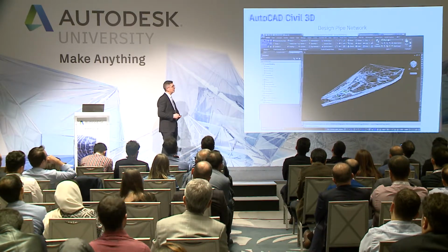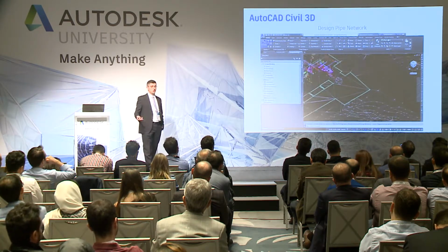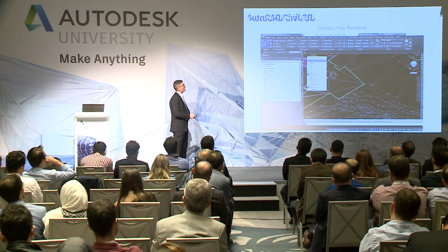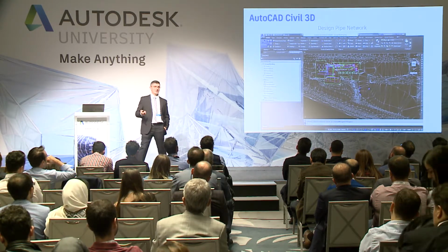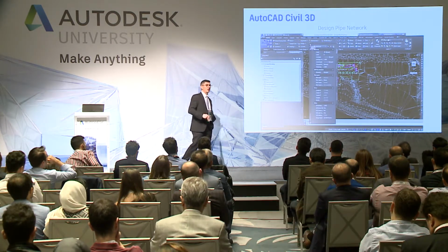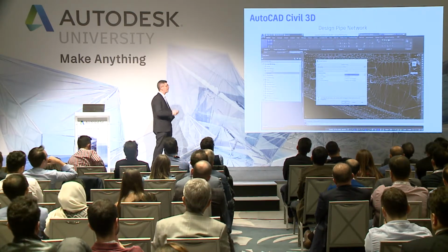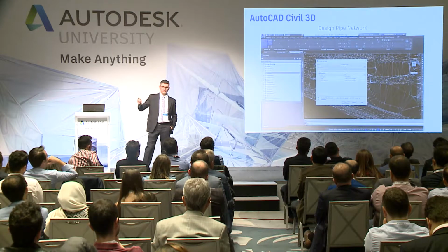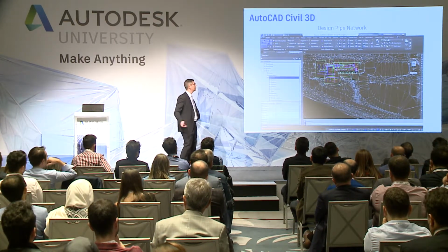Then the first one, again, this is the exportation, okay, like this. It's a DWG, easy for us. Then I can start to create, again, a surface, because the surface is the first step. In this case, we have triangles, and then we can manage the triangulation like a new surface. The first step is, please create a new surface: create surface, name, style, and which object do you want to add to the model.